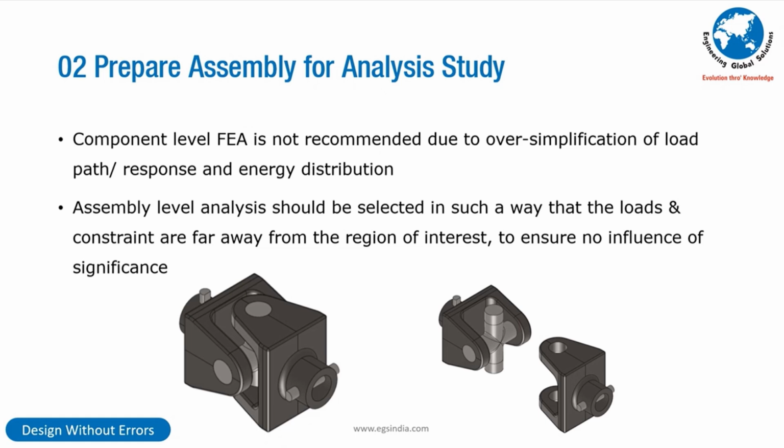If I am looking at the two yokes in addition to the trunnion as an assembly, remember, when I take the reliability calculations down the line, if the individual component has 99% reliability confidence factor, and you are putting the components together in a series as shown over here, the reliability of the assembly is going to drop, folks, as more number of components come into picture.